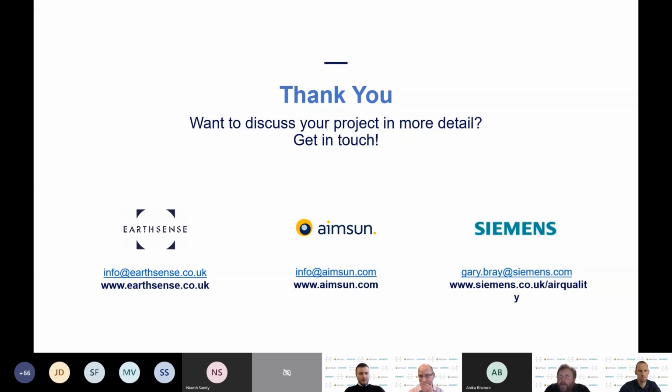Roland, do you want to add to that? Most of the answers are there. In most of our models, we do all of that vehicle profile emissions based on the Emissions Factor Toolkit and the partitioning, but all of that was done by Aimsun here, excellently. So we took that NOx emission, we partitioned that between NO2 and NO, thought a bit about the chemistry, and then obviously modelled the NO2 from there. But yes, most of the vehicle fleet profiling was done by Aimsun in this case.